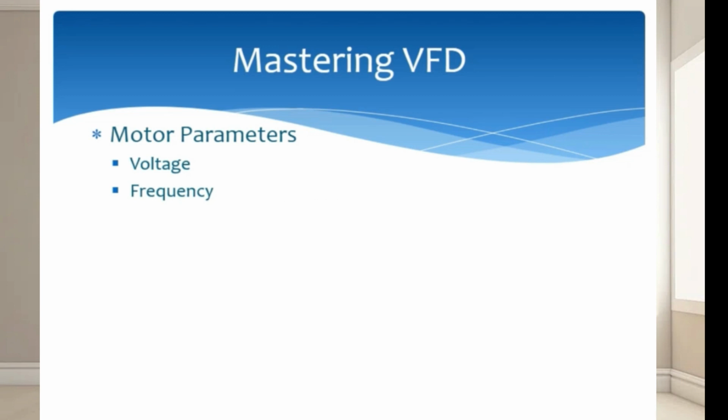Next, the rated ampere of motor and the motor kilowatts, that is the capacity or horsepower. So these four values are must to be known and programmed before any other programming. But there are few other parameters which we need to know if we want to use some advanced functions. These advanced functions we will check later in this course.